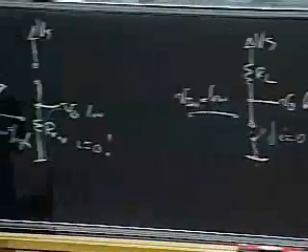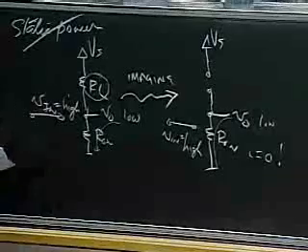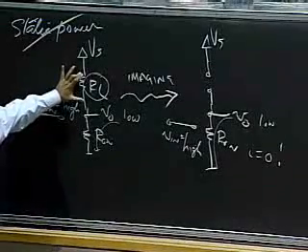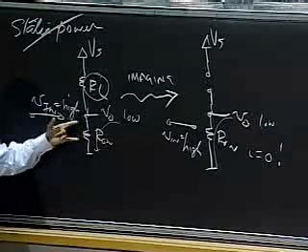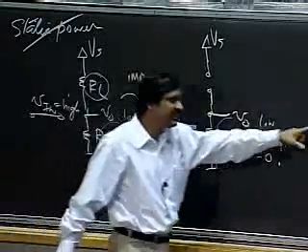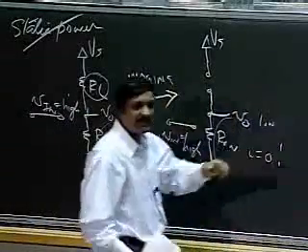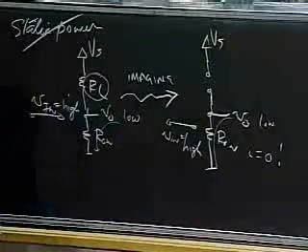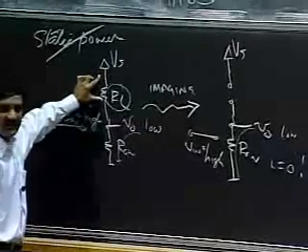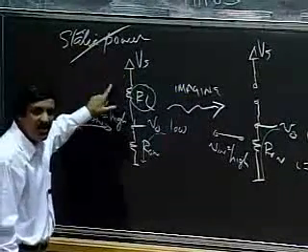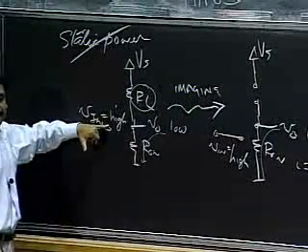Okay, so think about it. The intuition is that what I need is, instead of a resistor here, what if I had something like the MOSFET that I have here? So I had a MOSFET here that turned off when Vin was low. Okay, what if I did the complementary thing? What if I put in some kind of MOSFET here that would turn off when Vin was high?